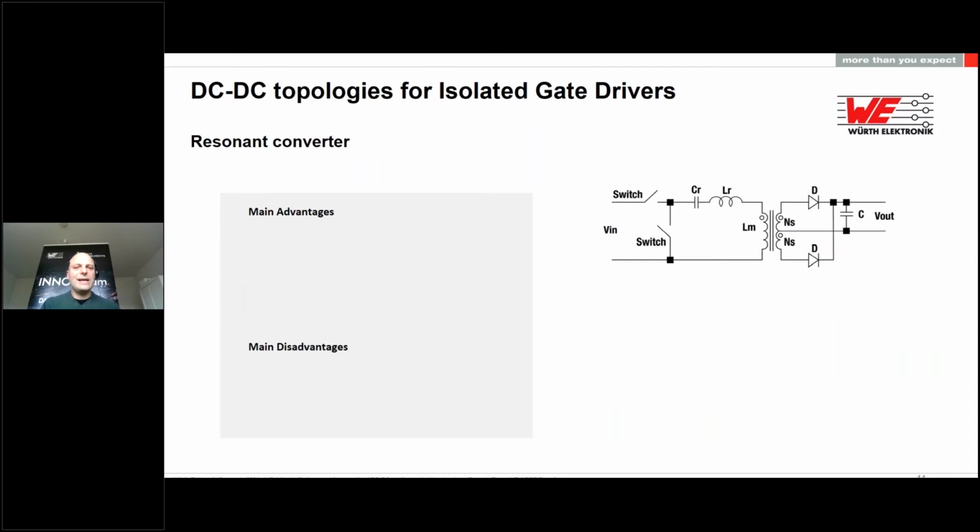The resonant LLC is a half bridge topology that uses a resonant technique to reduce the switching losses. Due to the zero voltage switching, it also achieves low EMI emissions. The transformer does not need to store the energy again. Usually, an LLC application is quite complex. It is frequency variable, requiring a lot of design resources and a relatively high number of components compared to a half bridge.